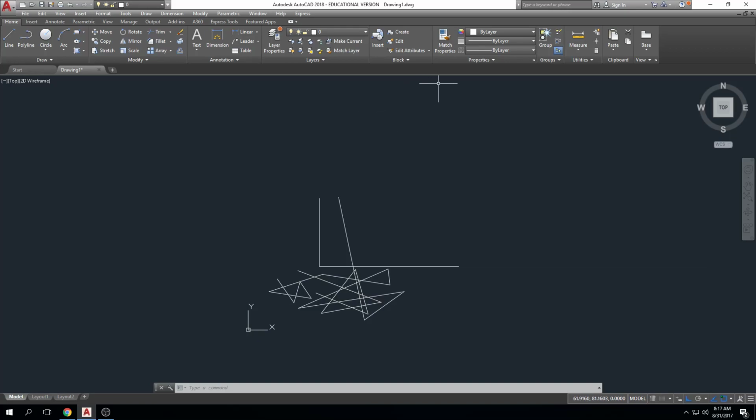Another quick thing just to remember is that your units in AutoCAD are going to be feet and inches, of course. And by default, those are not the units set in AutoCAD. So when we open up a blank drawing, we want AutoCAD to recognize our input. When we type in 15 feet, we want AutoCAD to recognize that's 15 feet, not to just disregard it or input something else. And because we are not the only professionals that use AutoCAD, we have to set AutoCAD to however we want it to be used, essentially.